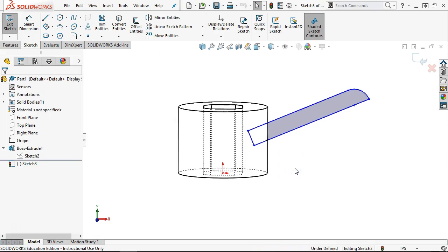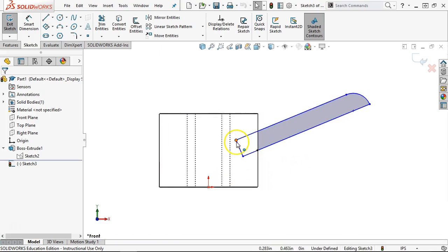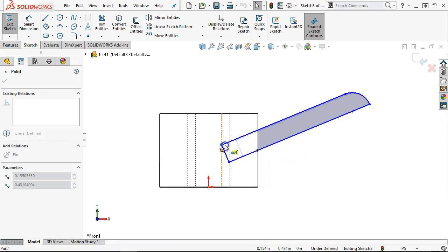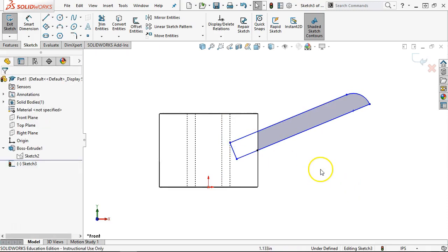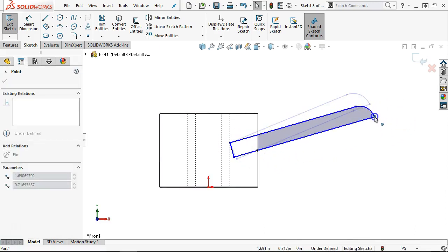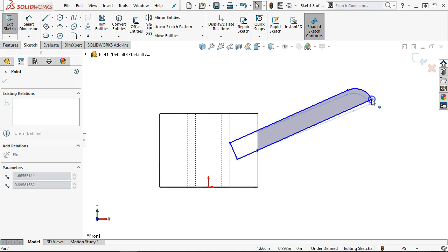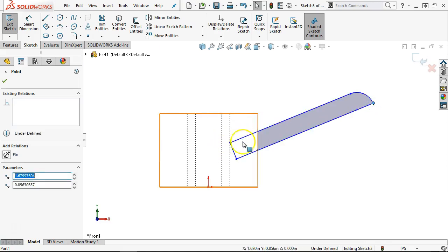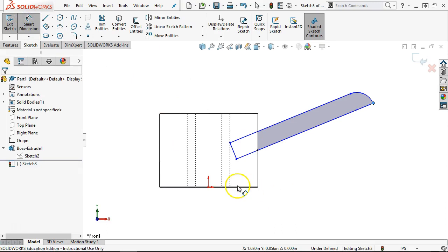All right, so back to the front view, Control 1. I'd rather not set a dimension if I don't have to, so if I were to make that coincident, then even though this is able to move and potentially change shape, I won't ever intersect that opening that I left. All right, I put it right on the edge, and that may be a good plan. It may sneak up on me later, but for now, we're going with the angle.